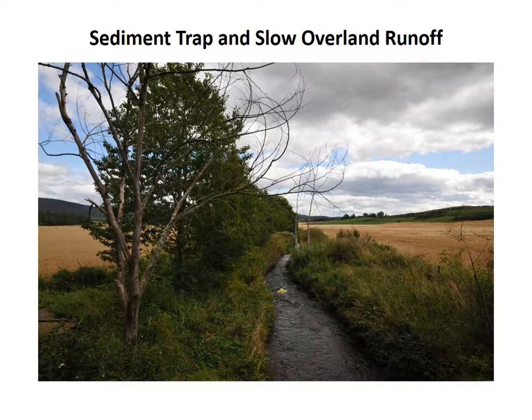Another consideration is to plant a dense herbaceous buffer between the edge of the cropland field and the beginning of the slope that leads to the riparian areas. The purpose of this grass strip is not only to stabilize the soil, but also to help trap sediment coming off the cropland field and to reduce concentrated flow into the riparian area. The most commonly used grasses for this include switchgrass, Indian grass, and eastern gamagrass, although species will vary by region. Farmers should resist their inherent urge to manicure, mow, or spray weeds in this buffer area after establishment.